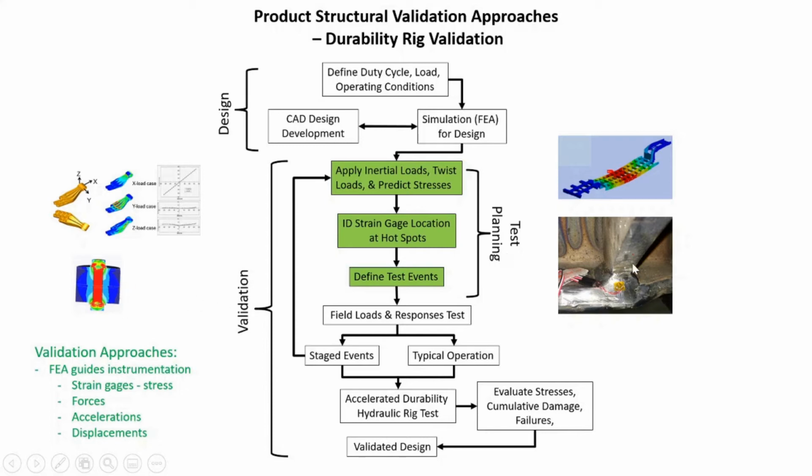Furthermore, the gauge locations are often going to be near welds. The welded joint areas are areas that we want to pay particular attention to, making sure that we have stresses in those ranges that are suitable based on welding standard curves and so forth.